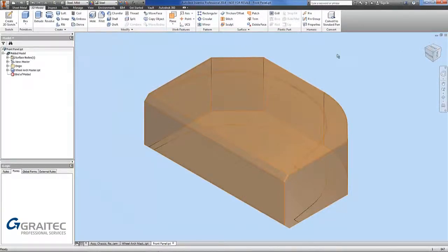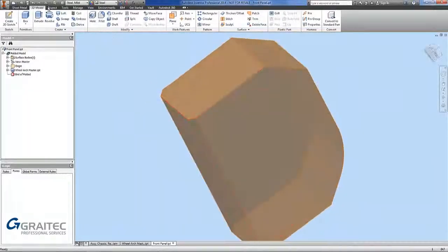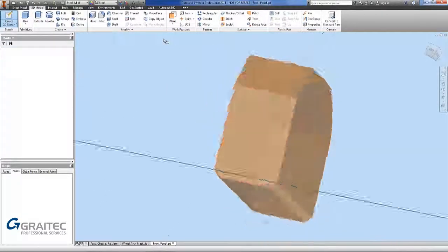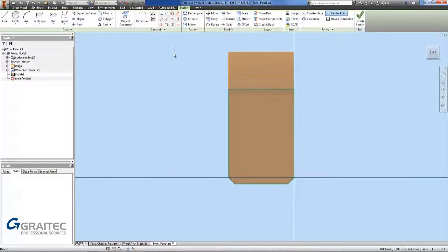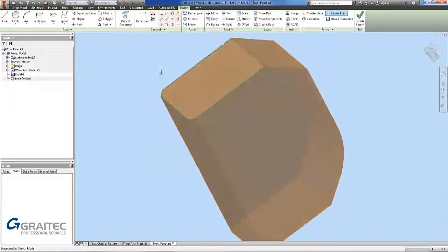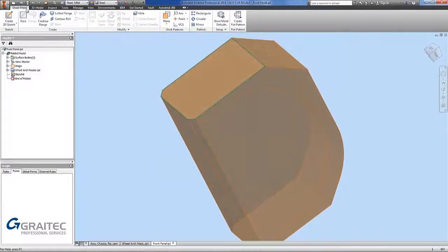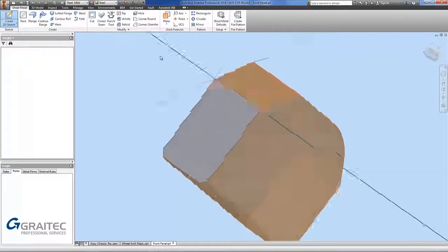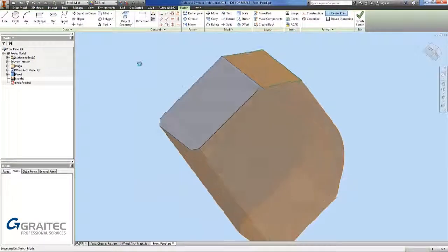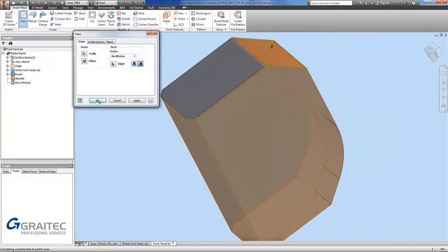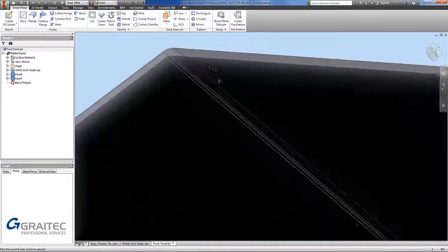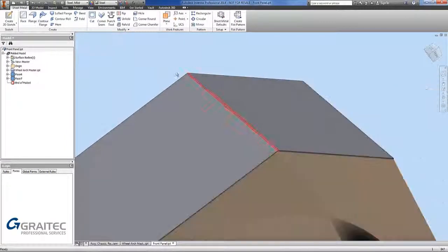What I can do now is use this to start creating my sketches very conveniently. So I'm going to go 3D sketch, pick the surface. With my application options currently configured, it projects the surface for me, all the edges. So I just go finish sketch, back to the 2D sheet metal tab, pick face, go OK, create another sketch, put it on there, finish sketch, pick face, go OK. It's created my surfaces and it's putting my bend radiuses in for me.